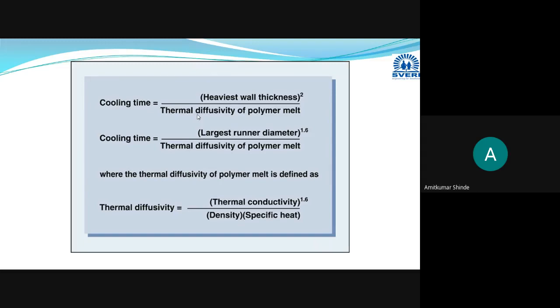Hence we have to avoid thick sections. Shrinkage will be more when thick sections are there as compared to thinner sections.